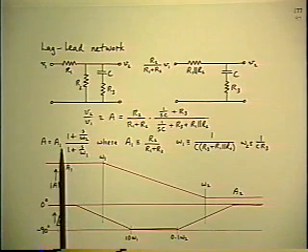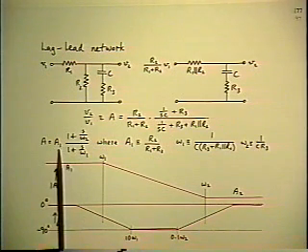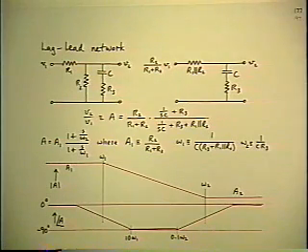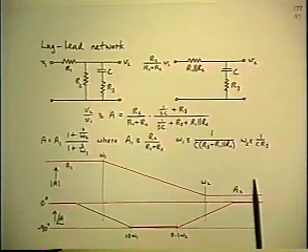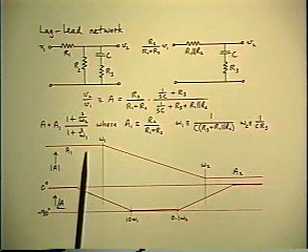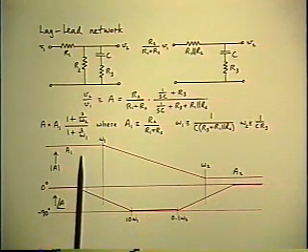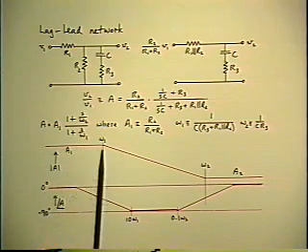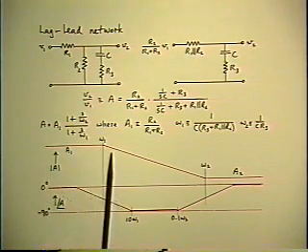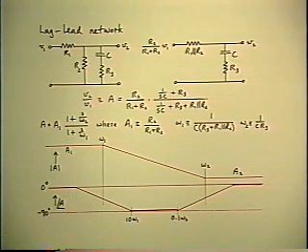And then, starting with the A1 as reference gain, at higher frequencies the pole and the zero will modify that result. So the next thing we want to look at is the sketch for magnitude and phase versus frequency that this network has. Starting from A1, the reference gain at zero frequency, as we go up in frequency we'll encounter either the pole or the zero, depending on whichever comes first.